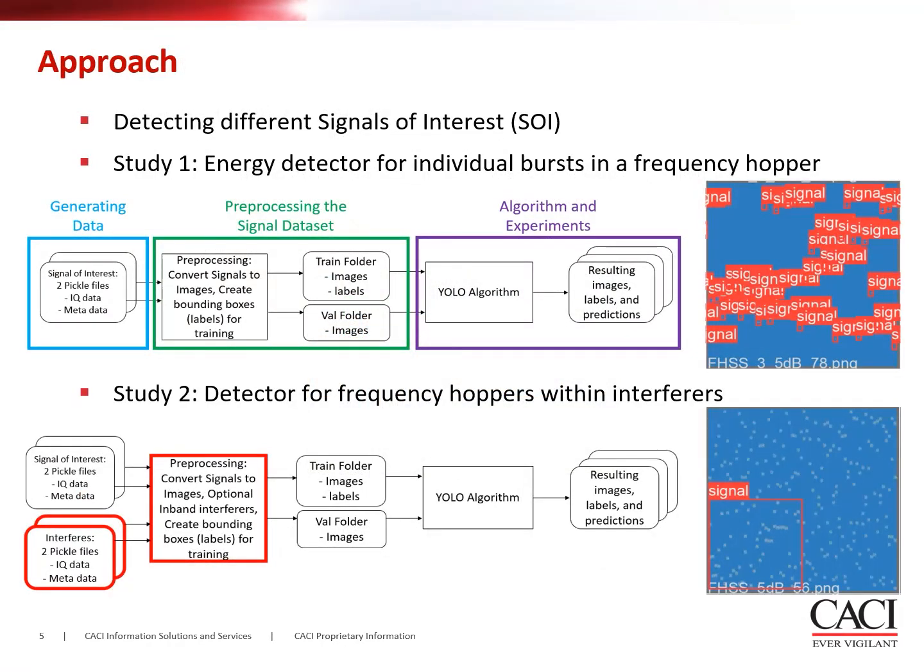This research leveraged baseband IQ data generated from synthetic RF waveforms for a variety of digital signal types with a focus on frequency hoppers. Spectrograms were generated from multiple power spectral densities of the data over time to form a 2D image. The spectrogram is similar to images commonly found in the Yolo dataset in that it is a grayscale 2D display of pixels. The accuracy of Yolo was evaluated on both narrowband bursts of energy and wideband frequency hoppers.